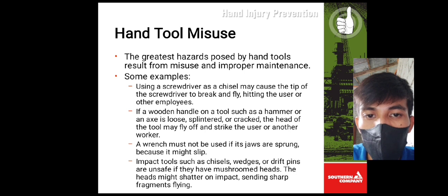A wrench must not be used if its jaws are sprung because it might slip. Impact tools such as chisels, wedges, or drift pins are unsafe if they have mushroom heads. The heads might shatter on impact, sending sharp fragments flying.